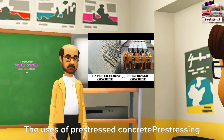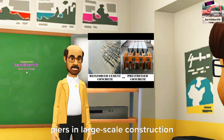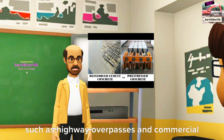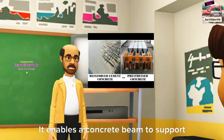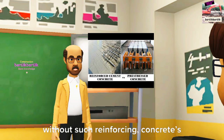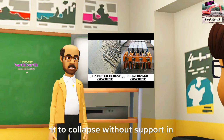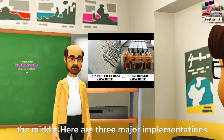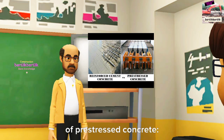The uses of prestressed concrete. Prestressing is used to make composite beams and piers in large-scale construction such as highway overpasses and commercial buildings. It enables the concrete beam to support weight between piers on either side. Without such reinforcing, concrete's lack of tensile strength would cause it to collapse without support in the middle. Here are 3 major implementations of prestressed concrete.